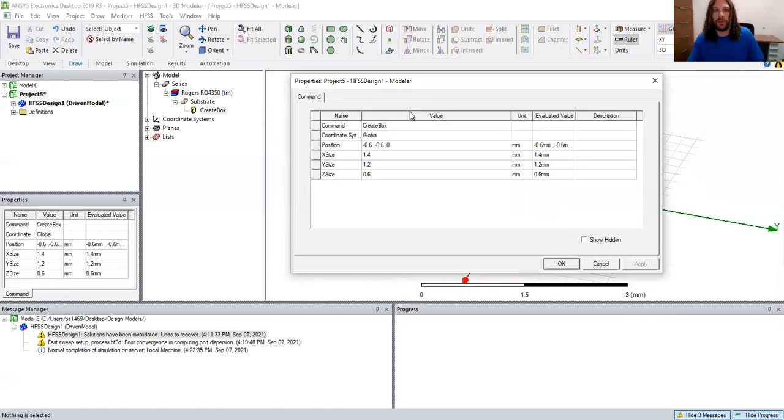So we're going to parameterize the dimensions so that we can change them later. I don't want to just say it's 10 millimeters long and then need to go back and change that at the end. What I'd like to say is it is substrate long, and then we can give substrate a value. So watch this. We're going to do negative substrate divided by 2, comma, negative substrate divided by 2, comma, 0. So these are our x, y, and z coordinates. It's negative substrate divided by 2, negative substrate divided by 2, and 0.